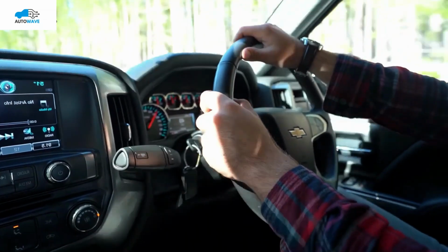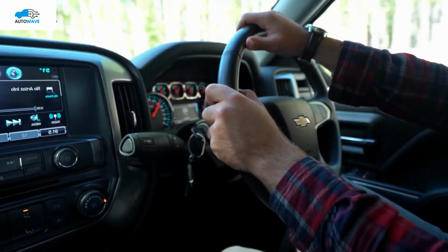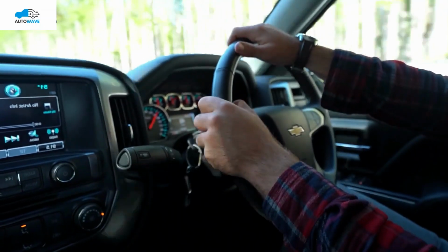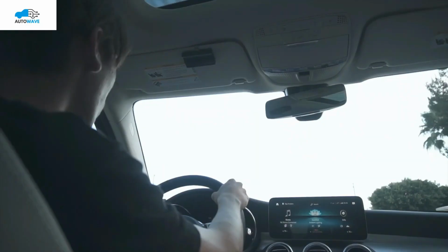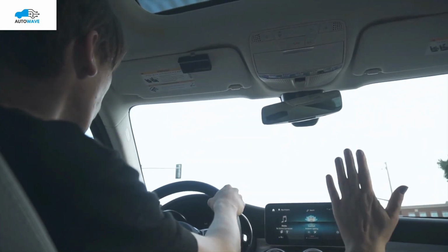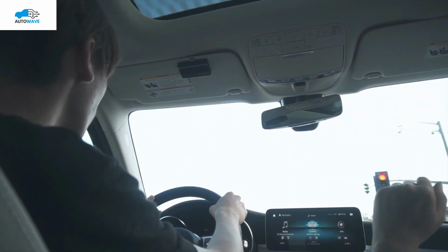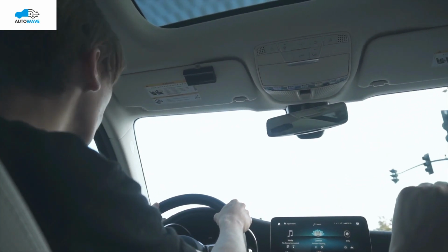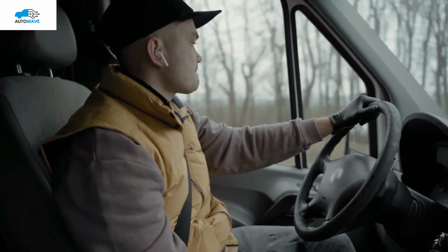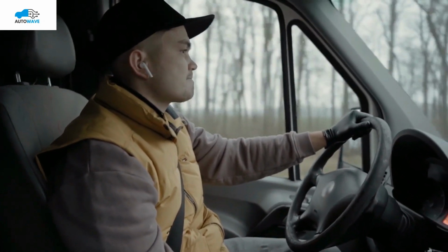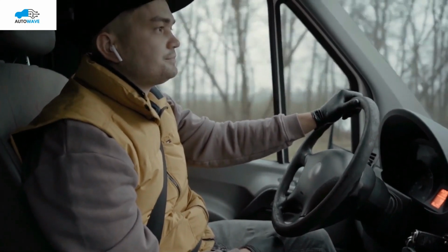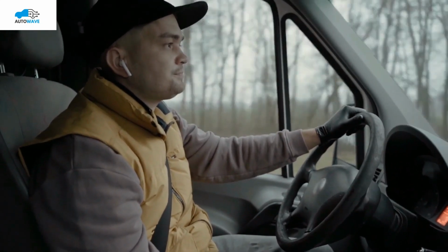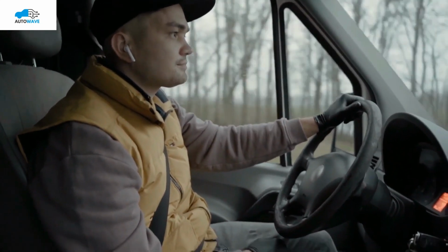As already discussed, pressing the Econ button reduces throttle response for efficiency. Econ mode automatically maintains RPM according to speed. Throttle response is mostly affected in the mid-range. When the car accelerates or slows down, this effect is lower, and it affects more in the mid-range where the car is continuously moving at the same speed, that is around 80 to 90 km per hour.